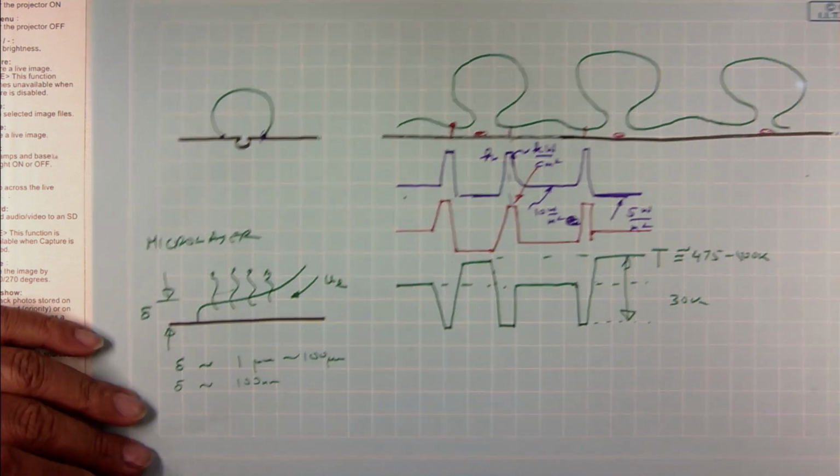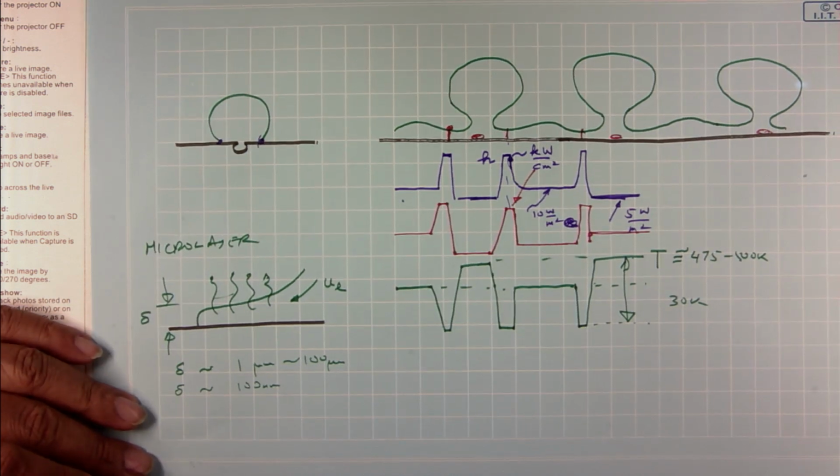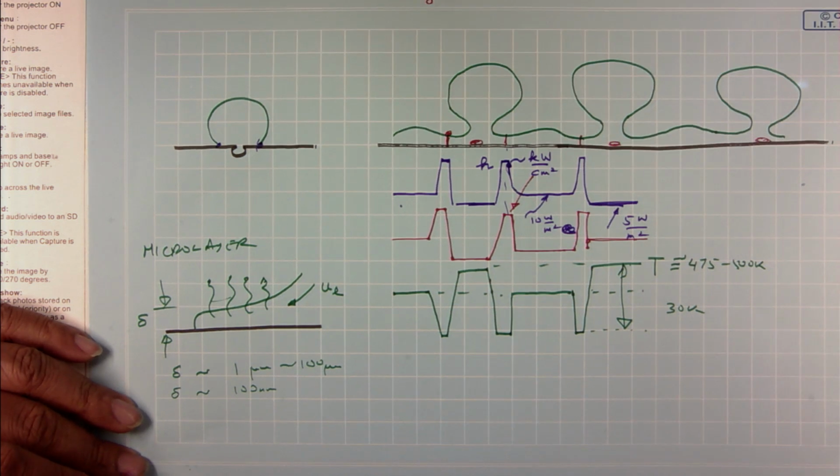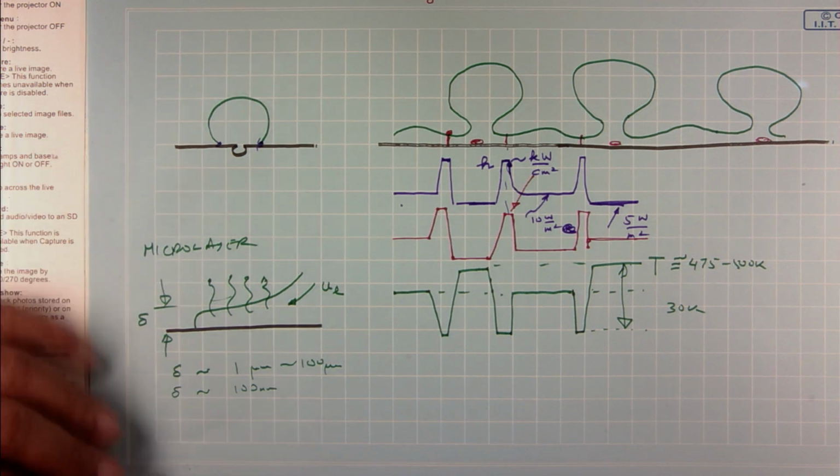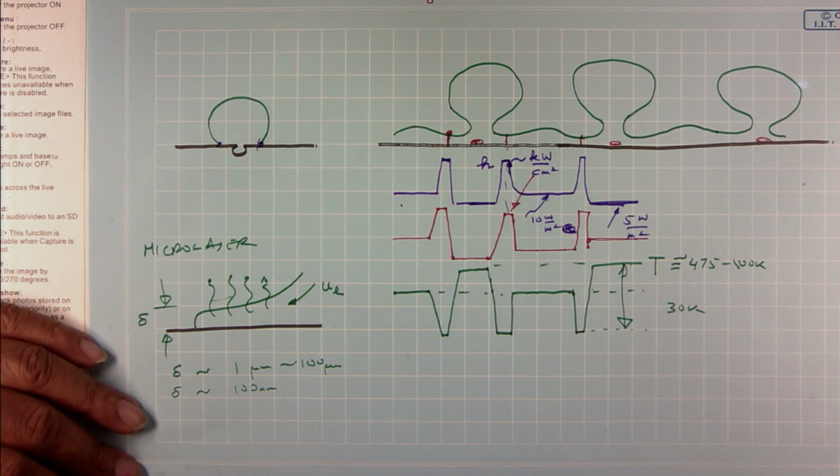Okay. So, if your thickness is below 150 nanometers, then you are totally clueless, right. And so, what people do is they measure up to about 300 to 400 nanometers, and then they draw an asymptote and they say, oh, at this location it goes to 0 thickness, and so it should be about 300 or 500 nanometers in thickness, and that is erroneous.